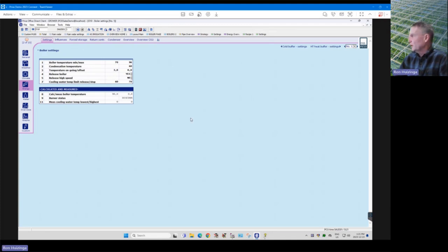So I was starting to talk about the boilers, and in I310 here, the minimum boiler temperature. Once it hits the end of the day and the boiler is not needed for CO2 anymore, and maybe the buffer tank is filled up enough for heat, it's going to shut off. And what it'll do then is slowly cool down. Like we're saying, this boiler is going to be running about 90 degrees between the min and max, because if it goes over the max, it's going to shut off.